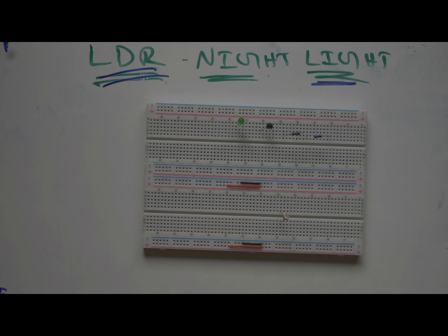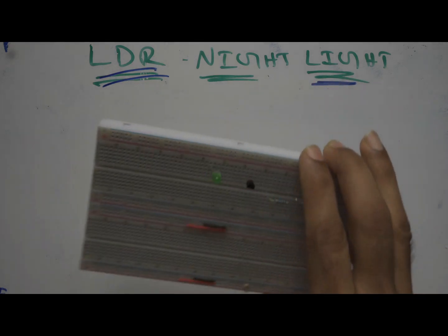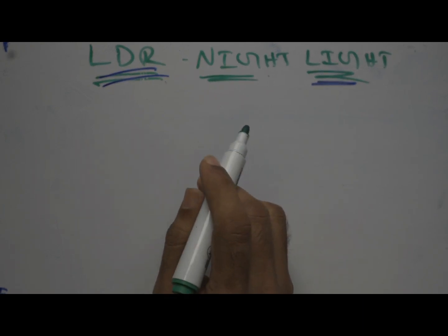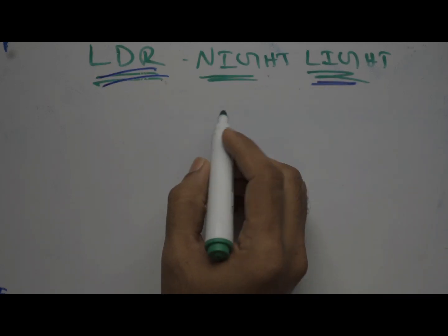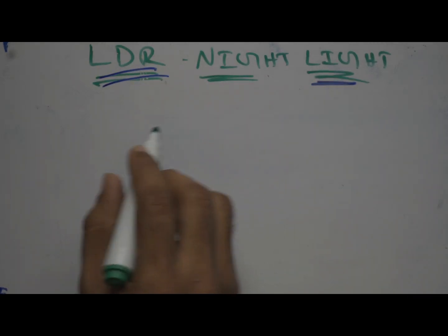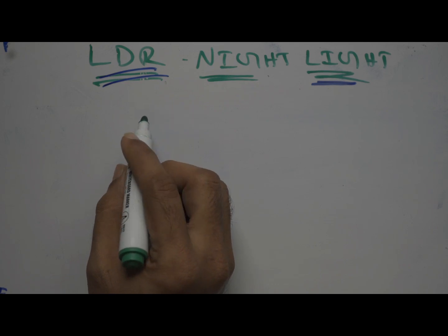And in street lights, they utilize a relay to drive high circuitry, a high halogen lamp as such. So now we will see how the circuit will look like. We will deploy a basic transistor BC547. I'll show you guys the pinout as well.